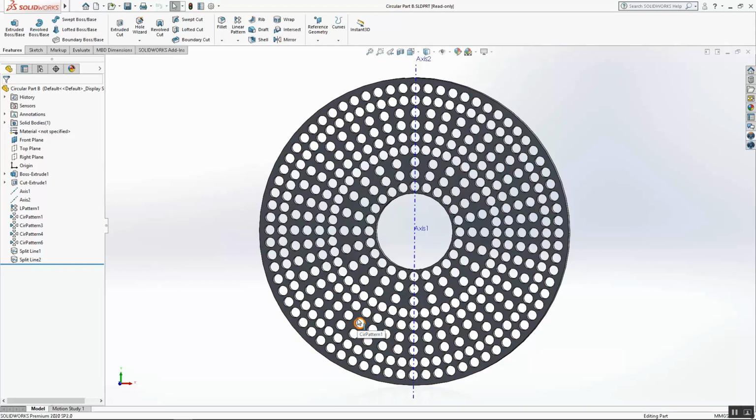collapse on one another. So if we were going to set this up inside of SOLIDWORKS Simulation, we would need to specify contact pairs. So you'd have to use a little bit of insight into figuring out which faces could potentially be collapsing on themselves, or which faces could be coming into contact with another face in another circle.